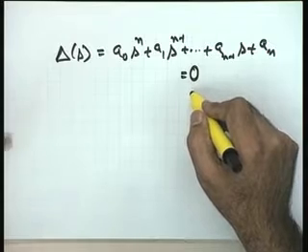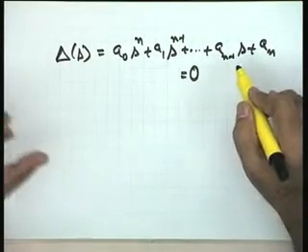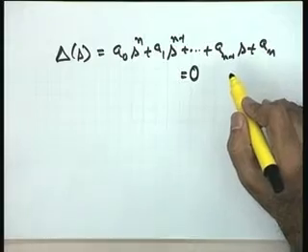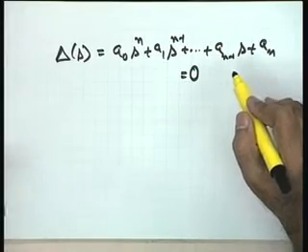You will recall the zeros of the closed loop system do not contribute to stability, because they simply change the magnitude of the response, they do not give rise to modes of the response. So, that is why in stability study we are not interested in the zeros at all, because they are not going to contribute to the stability analysis.